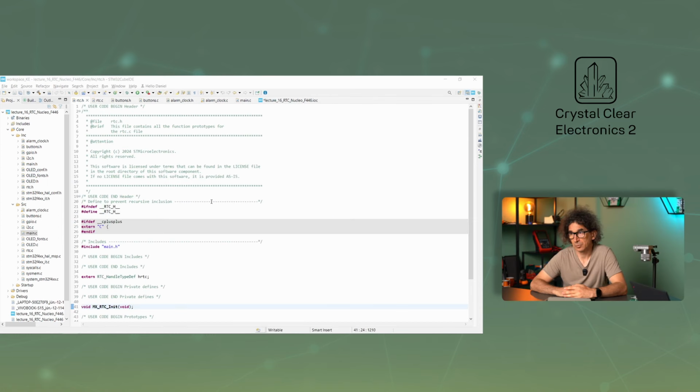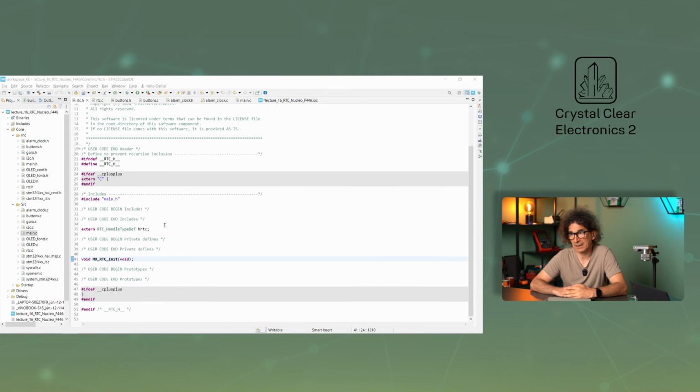The program lines for the real-time clock are written to the files rtc.h and rtc.c. The highlighted line is a variable declaration for an instance of the data structure describing the RTC. In the subsection HAL functions, we saw that every function has an input parameter hrtc. In this case, this is it. The now highlighted line is the declaration of a function whose task is to prepare and initialize the real-time clock.